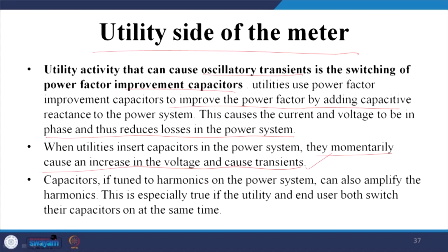Power capacitors, if tuned on harmonics on the power system, can also amplify the harmonics. That is also a problem. So, this is a problem that we discussed in detail in the case of the passive filters. Why is active filter preferred over the passive filter? There we will dedicate whole lectures to the designing of the passive filter.